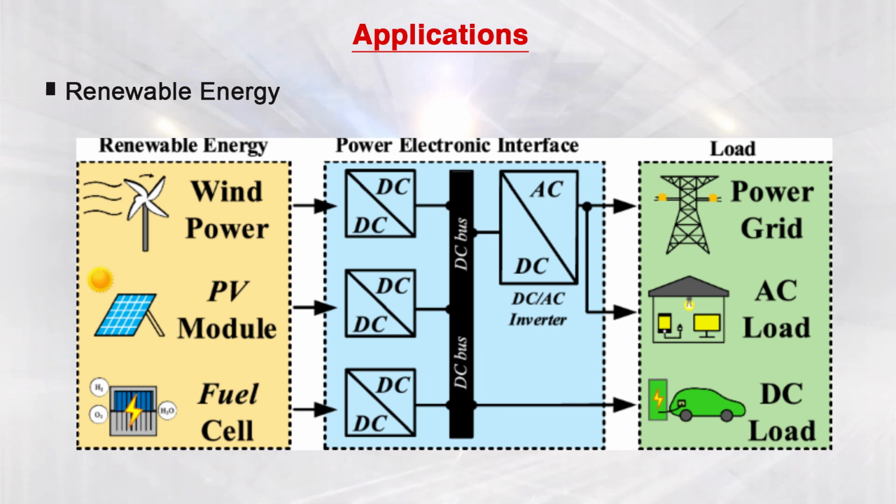And one important thing: these DC-DC converters are helping renewable energy sources so that they can realize constant impedance, because you cannot control the load, where the resistance is varying throughout the day. If the resistance is varying, your MPPT point may move left or right.